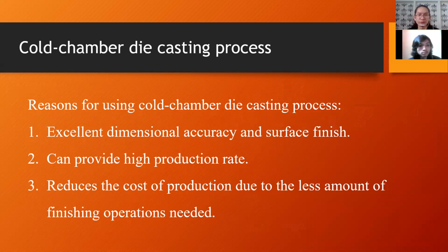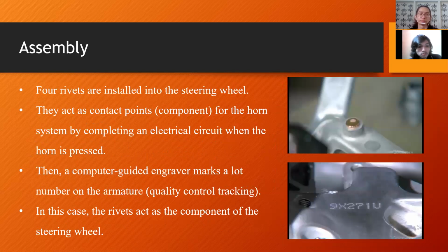The reasons for using the cold chamber die casting process are that it provides excellent dimensional accuracy and surface finish. It can also provide a high production rate and reduces the cost of production due to the smaller amount of finishing operation needed.